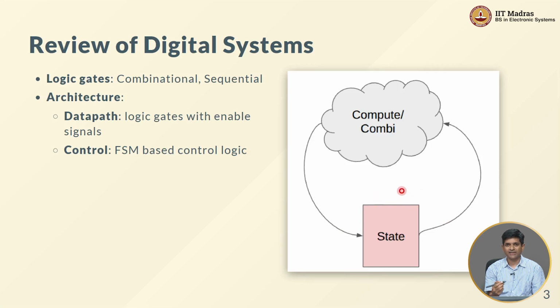And the present state of the system includes whatever are the intermediate states of those flip-flops as we are accumulating the final result. Therefore, this computation only needs to look at one specific partial product step that is being added in each cycle in order to get the final result.